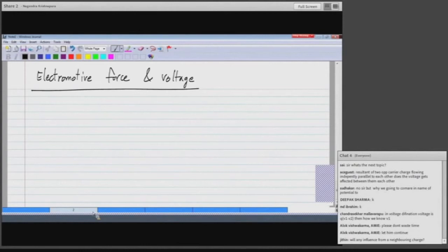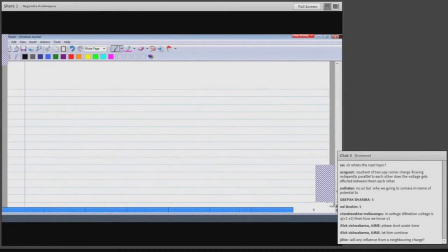Now what this says is that if you measure currents flowing out of the node, I will choose to measure the current in this direction. I call these I1, I2, I3, I4. There is a law that says I1 plus I2 plus I3 plus I4 equals 0. This has nothing to do with any particular circuit, but this is true for any circuit.